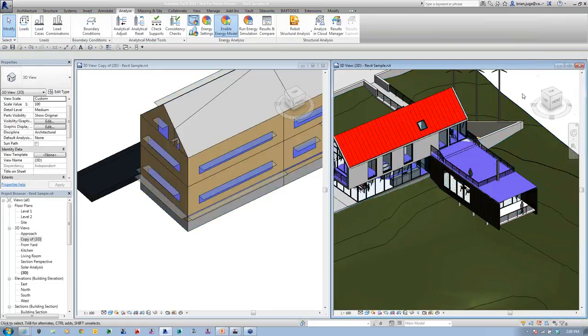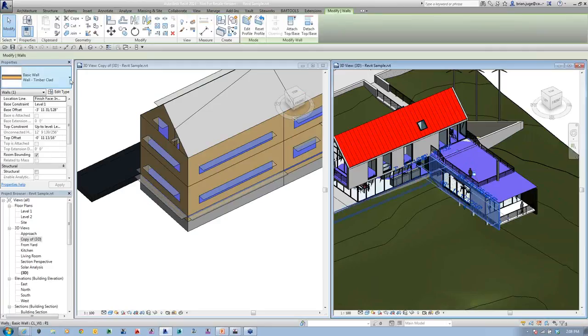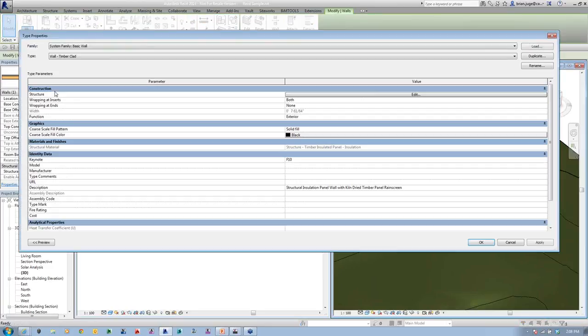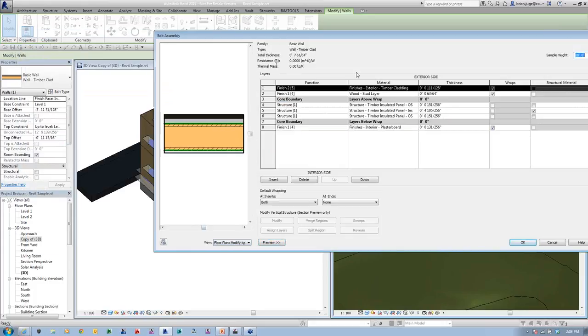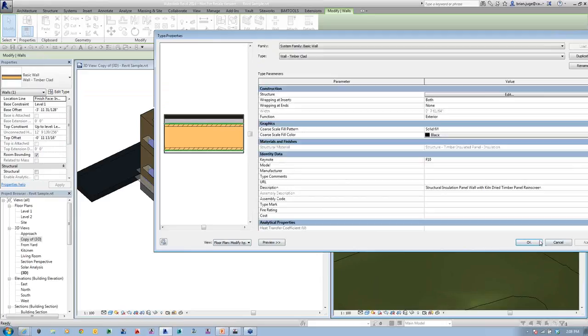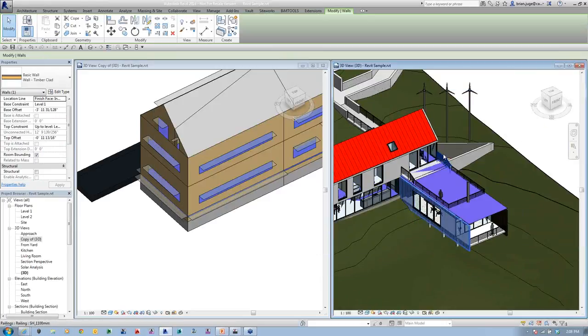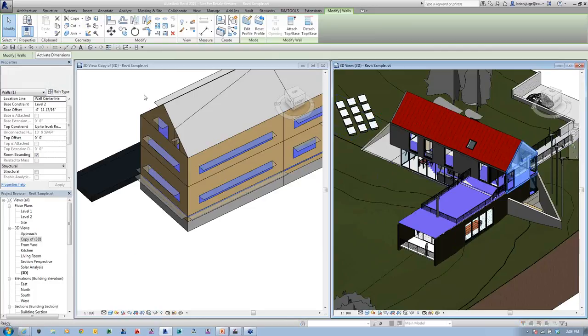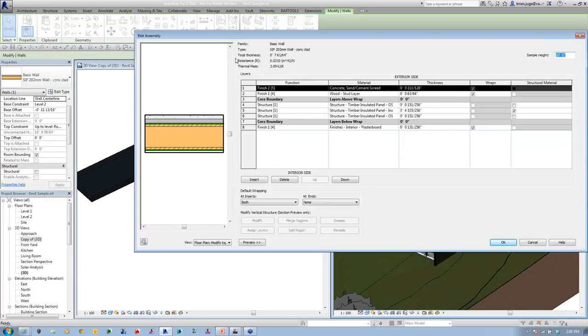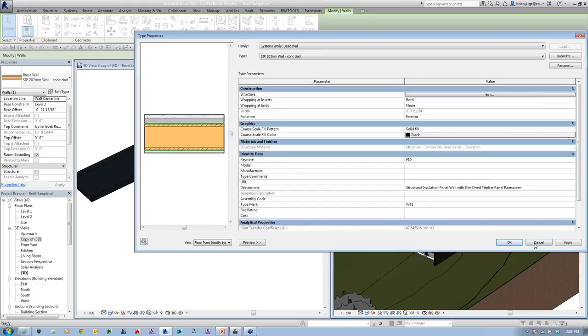in that particular view, and just talk about what we can look at now that the building's developed. One of the things we have in here is the wall type, and we can see in this preview we've got our resistance values. It's not showing up in this wall. It's going to show up if I put it on one of these walls in here. Let me grab that one. We're going to get some thermal mass that we can look at, the R value that's involved within here. And this is all based on the materials inside of Revit.